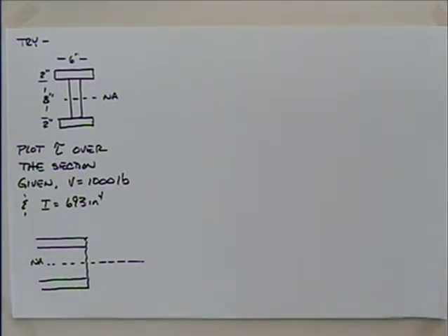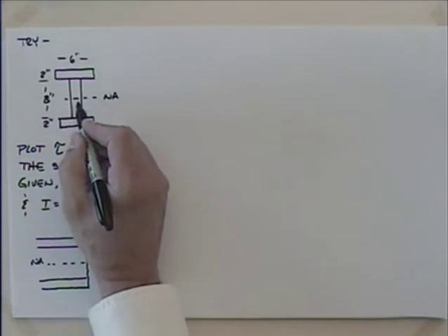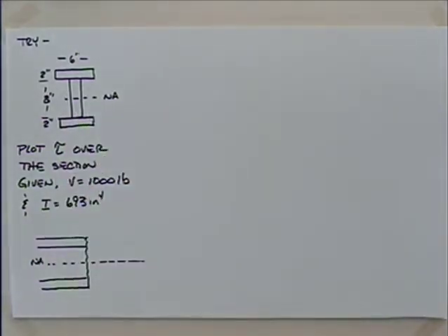Remember that your fingers, what do they call your fingers sometimes? Phalanges. And what's the little piece of skin between your fingers? Your web. A web of skin there. So you have the flanges, and then between the flanges is the web. So that's a fairly easy way to remember that. And when we look at a beam like this, the top and the bottom flanges are all about carrying the bending predominantly, whereas the web is all about carrying the shear. Okay? So that's kind of what's going on in that I shape there.